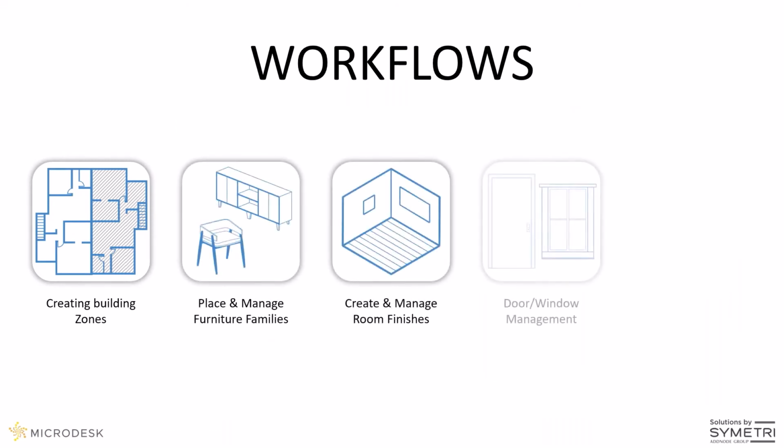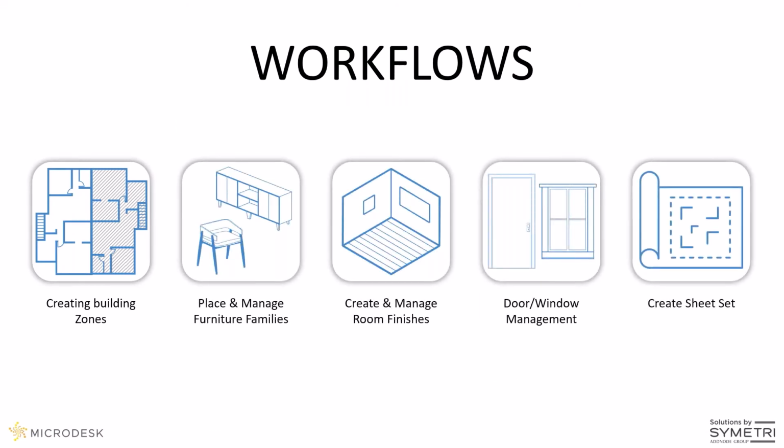So I just wanted to give kind of an overview of what we just looked at, because there was a lot of information there. We looked at creating our building zones, drawings of our different apartments really easily, being able to push data from those Revit areas to our Revit rooms, generating 3D elements from them, and creating our dependent views of the different apartments.